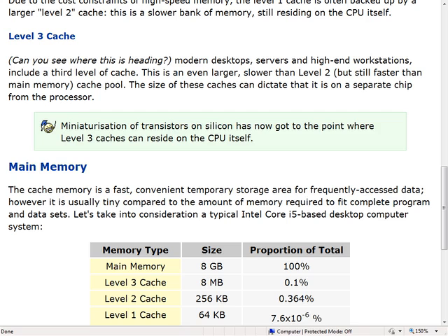In the past, you had the level 1 cache really, really close to the processing units of the CPU, and the level 2 cache could have been on the processor die, or right next to the processor, or even in the same socket. If you look at an Intel Pentium Pro processor, from about the mid-90s, the chip's actually really, really big. It's got this little gold cover over it, and if you take the gold cover off, there are actually 2 pieces of silicon on this package, like the packages we were talking about with the sockets, those square things. One of them was the processor and the level 1 cache, and the other one was the level 2 cache. That was because they wanted it to be as close as possible to the processor.